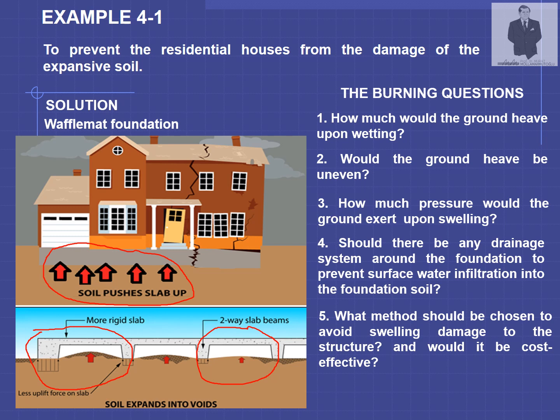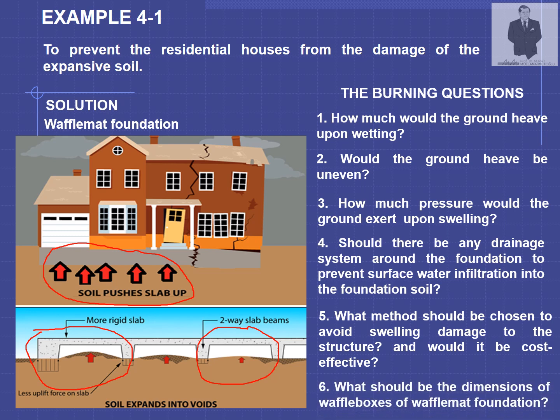And in earlier explanation, we said that there may be several possible solution methods, but we should choose the economic one among the best possible solutions. So when you compare these with mat foundation, you can easily understand that in here you will use less concrete, less reinforcement.